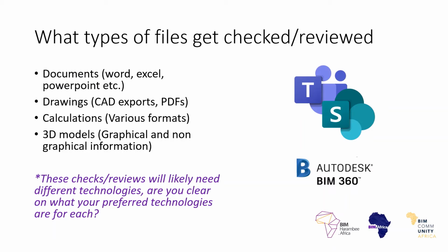And then on models, definitely new players in the market like BIM 360 model coordination. We're starting to use that a lot more when we're doing 3D model reviews. But applications like Navisworks are still the go-to for more complicated projects, when you have to federate models from many different applications and models are quite complex.